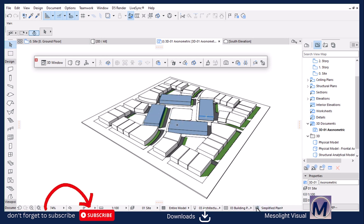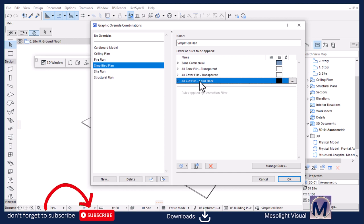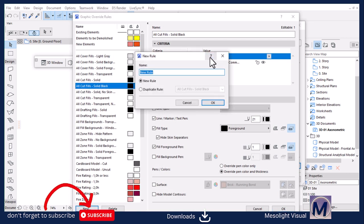So we go back to the simplified blend graphic override simple. What we need to do here first is go back to the all cut field solid plate, because remember, this is the base. It affects everything that is in the model. So if you don't exclude other elements within this rule, even if you create a new rule, let me show you what I mean. Let's create a new rule.